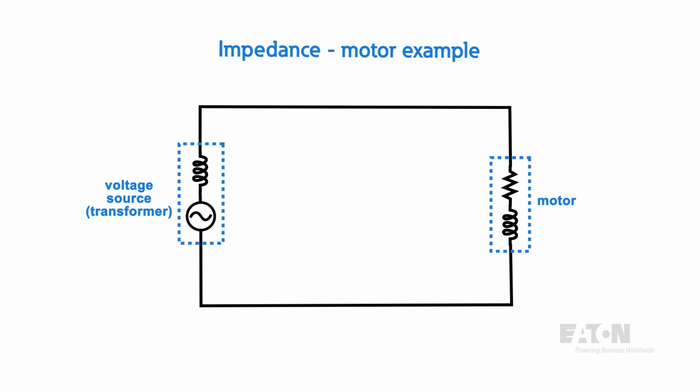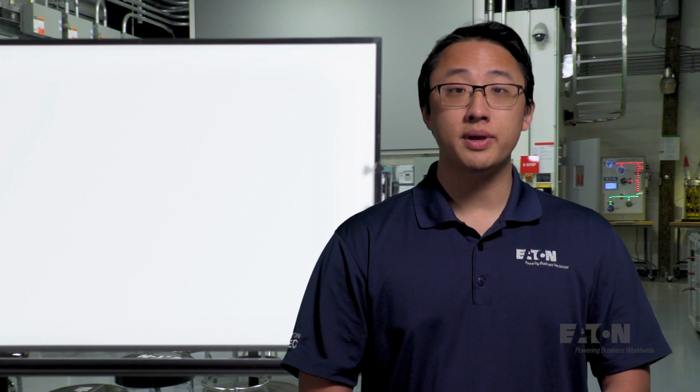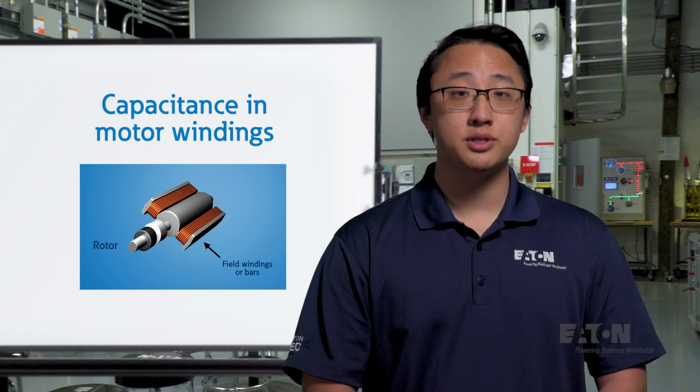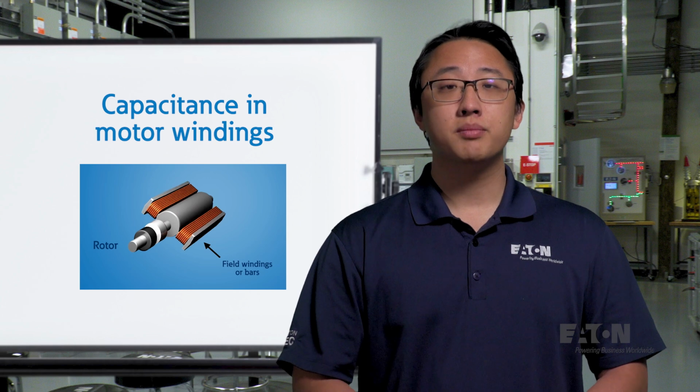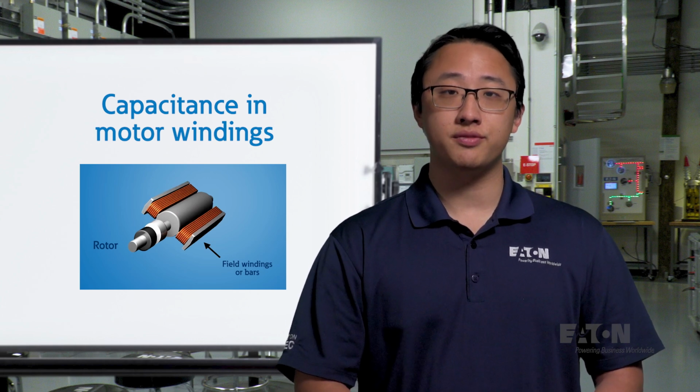Now notice the lines that we drew to connect the components. We often take them for granted, but in reality they represent something physical, wire and bus, both of which have impedance as well. Back in our reference, we see that generally, small conductors have very low X/R ratios, but as they get larger, it starts to balance out, so it could be represented as either a single resistor or a resistor in series with an inductor, depending on what type of wire we use, which itself would depend on the size of the motor. Depending on your purpose, you may also want to include the small amount of capacitance between the windings on a motor. This sort of detail isn't normally needed for power system analysis, but it is necessary for analyzing individual component failures.